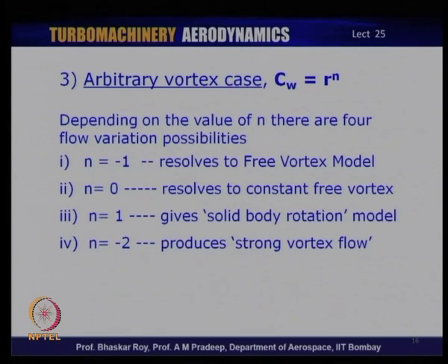If you put n equal to 0, it resolves to a constant vortex law, not constant free vortex, but constant vortex from root to the tip of the blade.